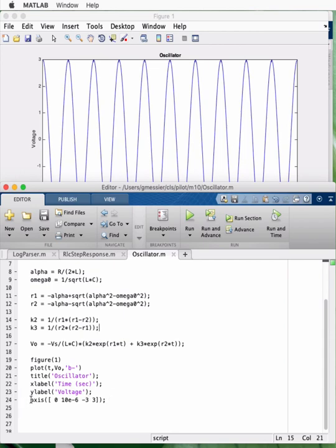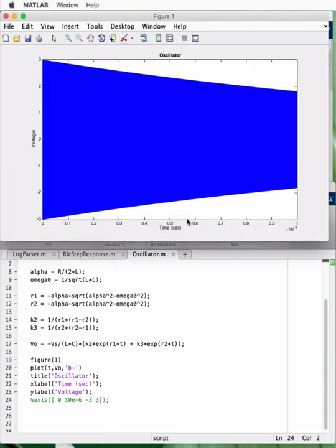Let's zoom out and take a look at a whole millisecond. So when we do that, we can't see our oscillation. It looks like a solid block, right? Because our waveform is oscillating so fast that we can't see it when we zoom out like this. But we can see that even after just 1 millisecond of operation, we've already decayed from a peak-to-peak voltage of 3 volts to a peak-to-peak voltage of less than 2, right? So clearly, if we want to run our circuit for a while, this 10 milliohm resistance does start causing us problems.